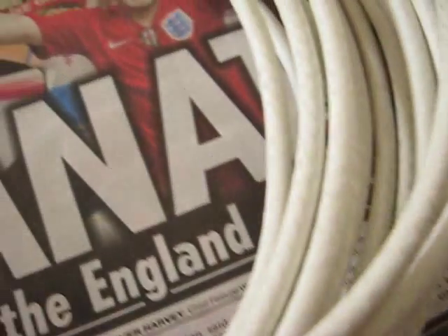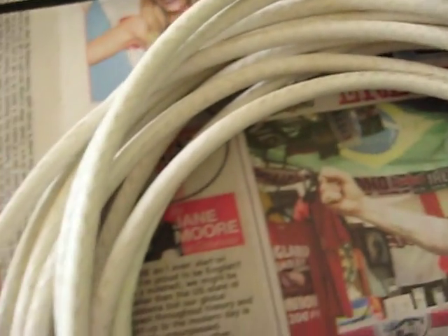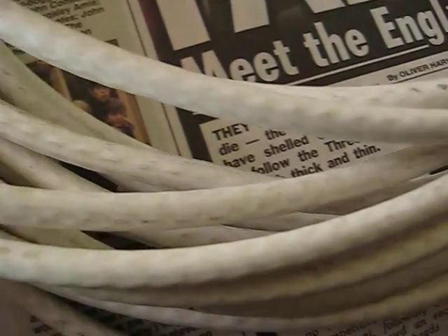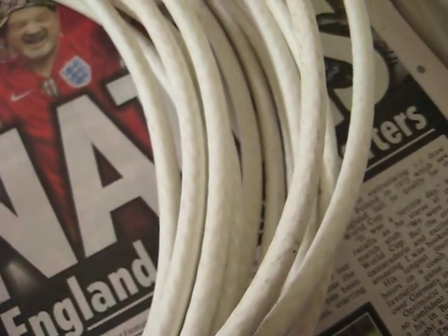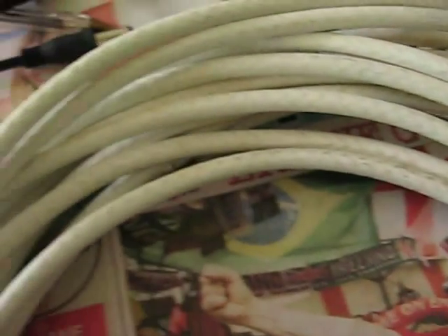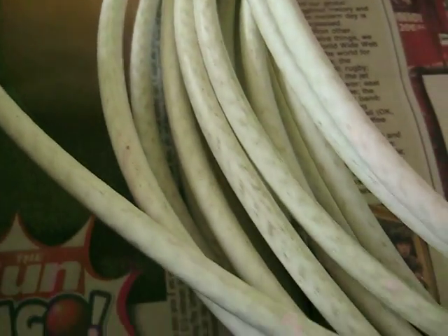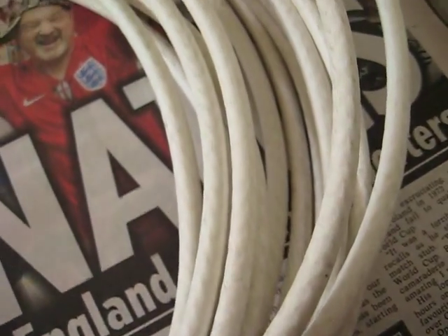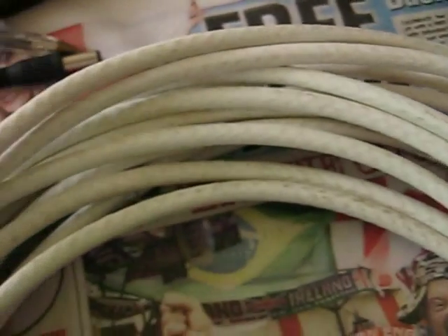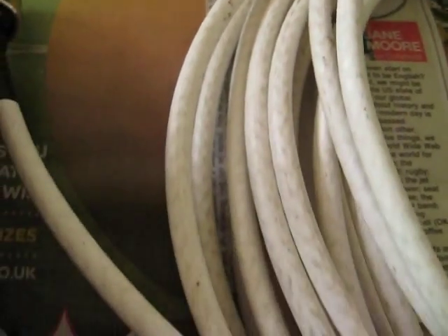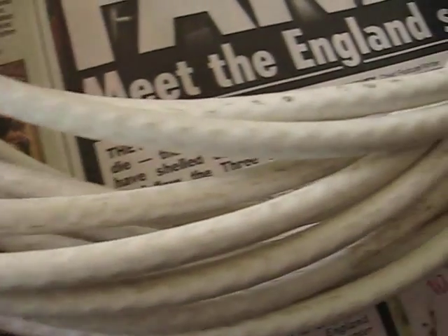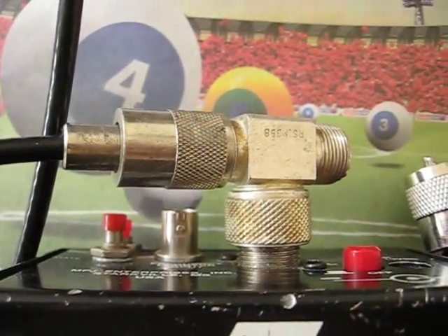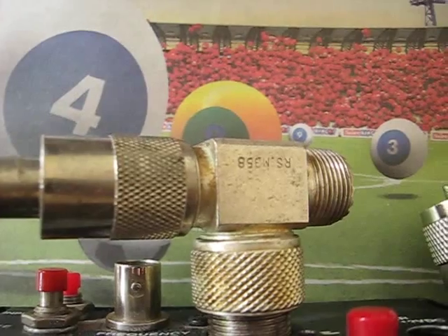You cannot test it coiled up like this. Must be laid out on the ground or hanging from the air if it's already connected to something and you're disconnecting it at the antenna to check for a half wavelength or multiples of. So that's all you need on your antenna analyzer.